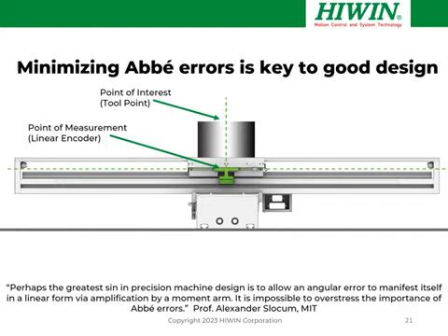So any deflections that are occurring in the motion system, and remember again, those 6 degrees of freedom, will result in errors at the tool point. So deviations from where the encoder thinks the tool point is versus where it actually is. And those ABI errors are the most troublesome. Why? Because they amplify by that offset distance. So the distance between the tool point and the measurement point multiplied by the sine of the offset angle equals your ABI error. So let's take one simple example.